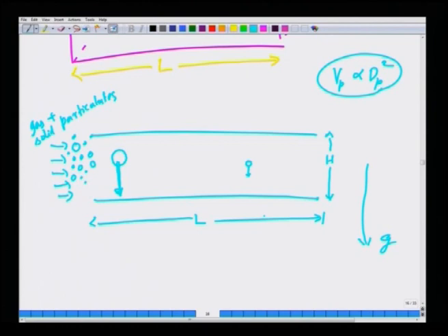Suppose you have a settling chamber of some length L and gap width h. What is the smallest particle that you can capture typically in a settling chamber? So let us start with some position A here. Now, if this particle has to be trapped over a distance L, then it must travel a distance of h within a time wherein it resides in this settling chamber.